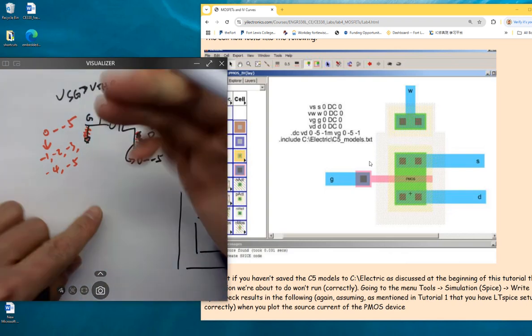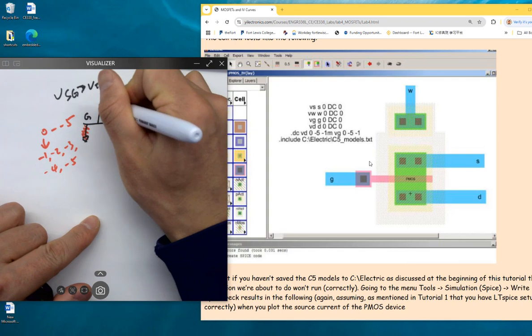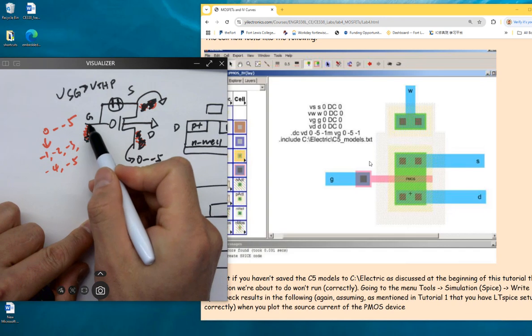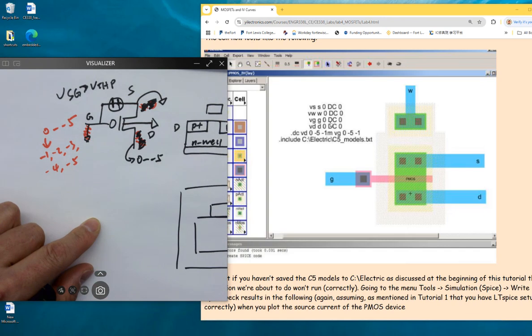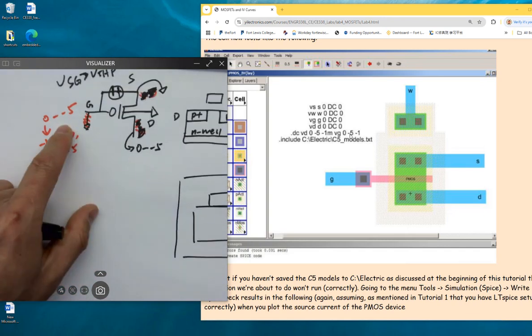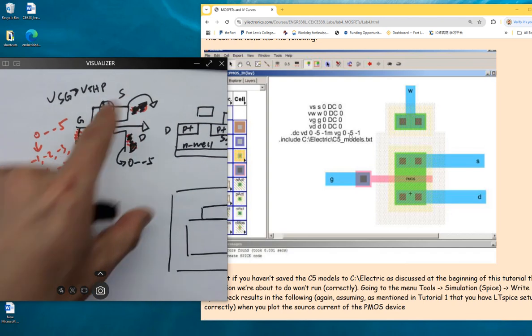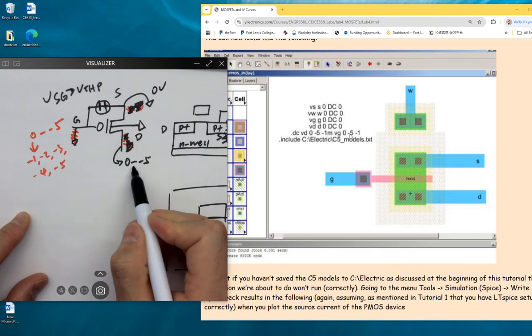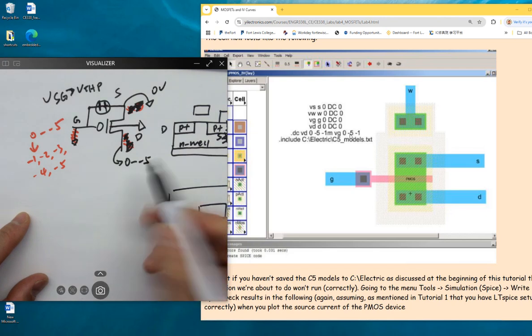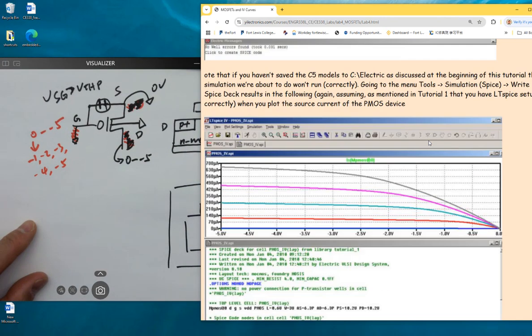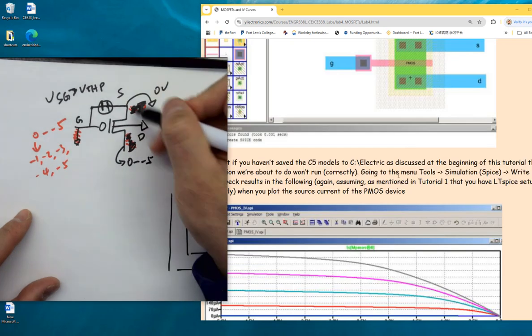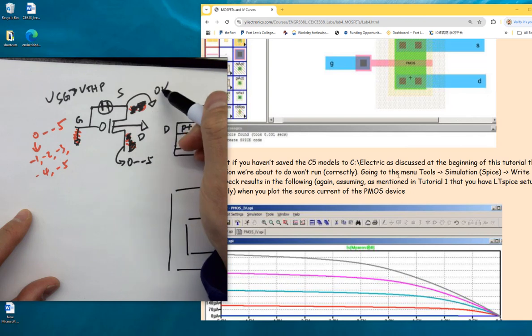So eventually there's a voltage drop over here, because of V gate. The gate voltage is negative, so you do have a VSG. And because here's 0 volts and VD is from 0 to -5 volts, sweeping on the x-axis like this, you are getting a positive VSD drop, even though source is ground.